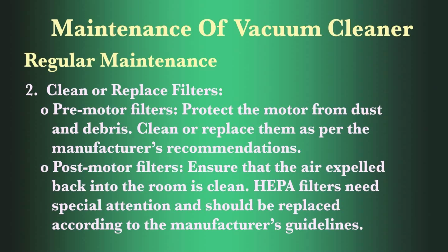Number 2 is clean or replace the filter. Pre-motor filters and post-motor filters. The pre-motor filters protect the motor from the dust and debris, and you have to clean or replace them as per the recommendation given by the manufacturer. Second, the post-motor filters, which actually ensure that the air expelled back into the room is clean. HEPA filters, as mentioned, need special attention and should be replaced according to the guideline provided by the manufacturer.